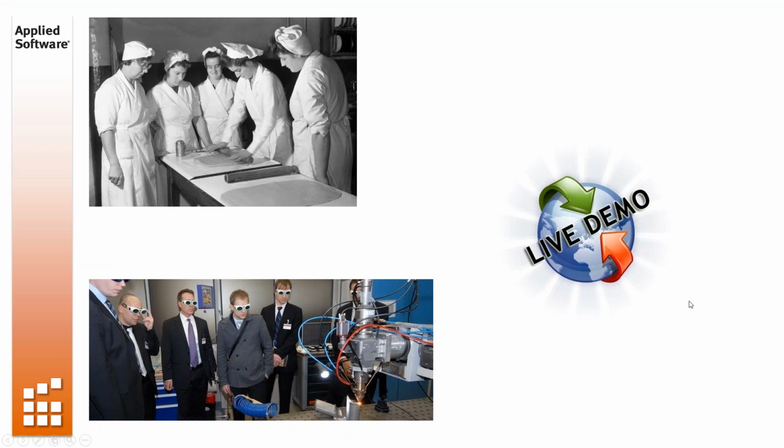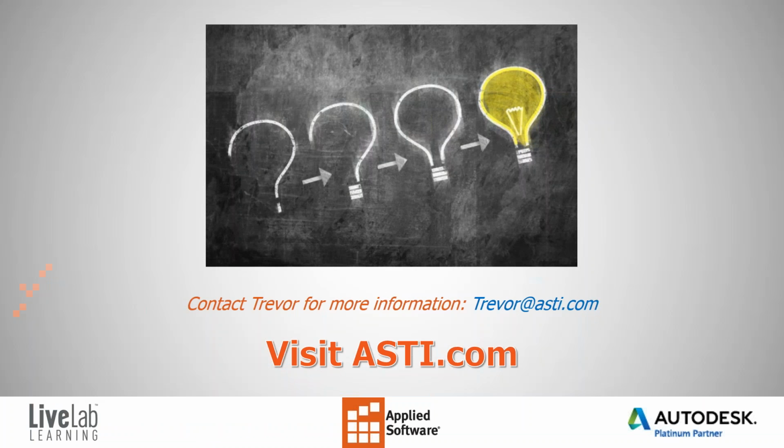We did have a couple of questions that came in during the presentation, one of which we get quite often: is Vault Professional included with Inventor Professional? The answer is no. Vault is a separate package altogether from Inventor Pro, but it does have an integration. If you're checking files in and out of the Vault, there is a toolbar and a workspace inside of Inventor, so you're not opening two separate screens and you're able to check in and check out your files.